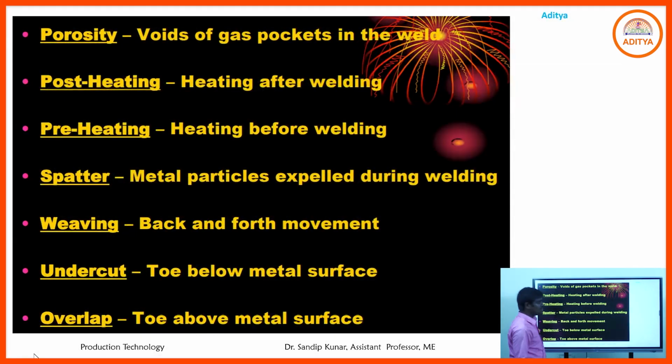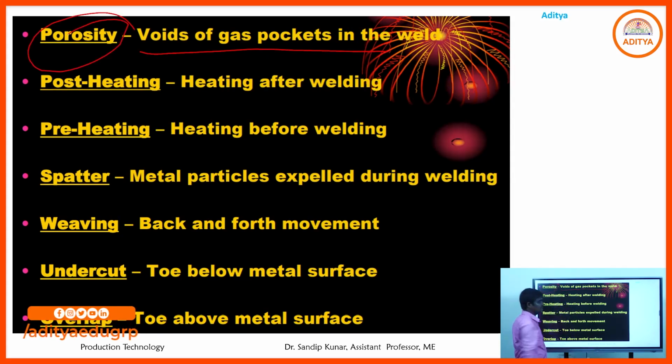Now porosity: during welding, some voids will be created. Voids are gas pockets in the weld, meaning some gas entrainment occurs, and due to that, voids are created during welding. That is the porosity. Post heating means heating after welding. After welding we do some heating, and that is called post heating.